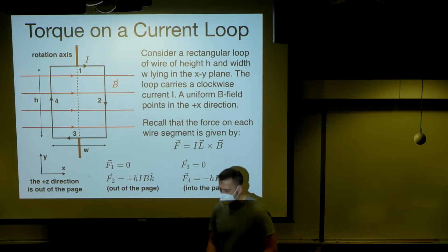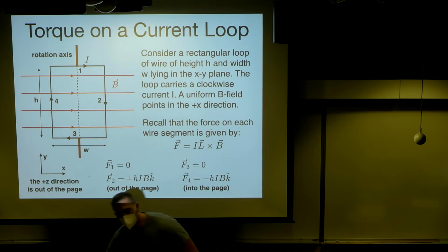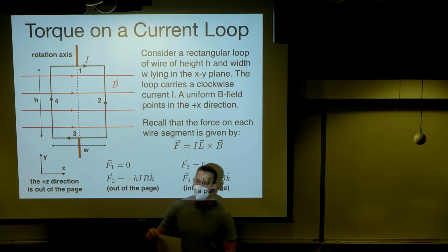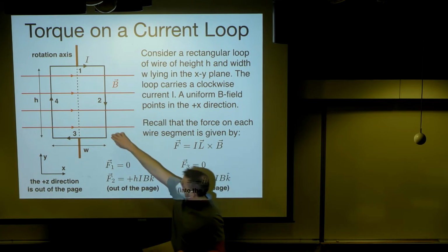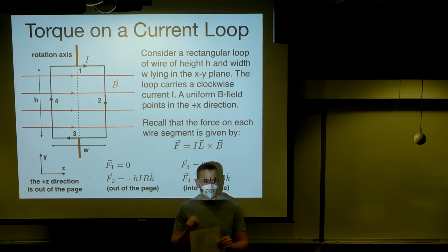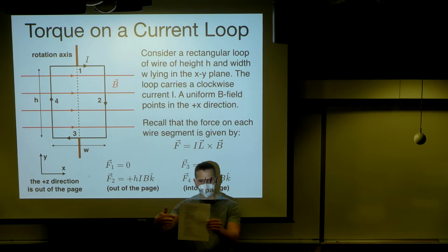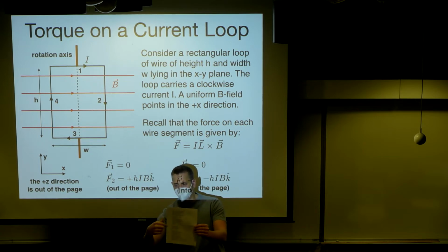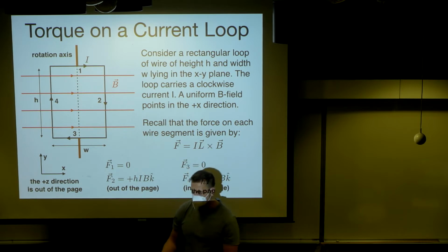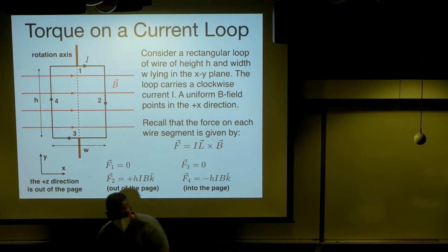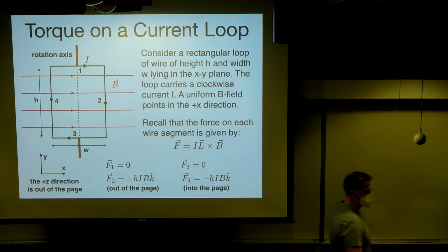Okay. Now again, just try to picture what's going to happen here. I hope you can already see that we have a torque happening. Okay? Because on this side, we have a force coming out of the page like this. And on this side, we have a force going into the page like this. So if you think about the combined effects, it's going to start rotating. Okay? So the overall effect is to induce rotation.